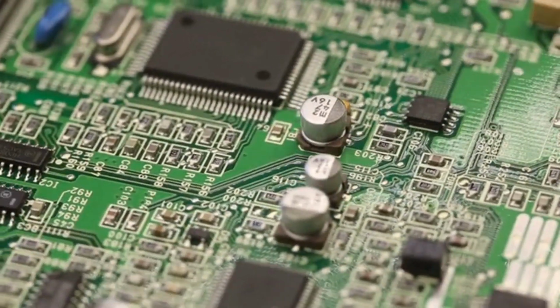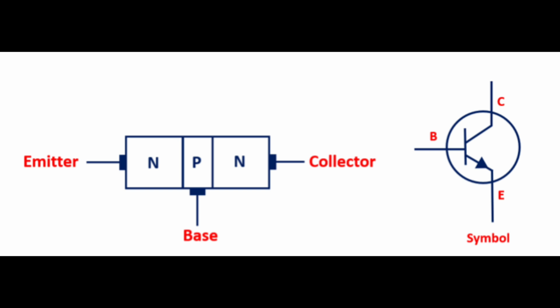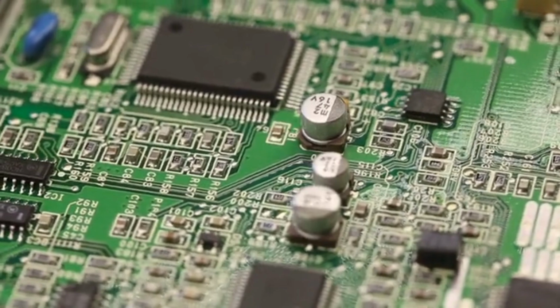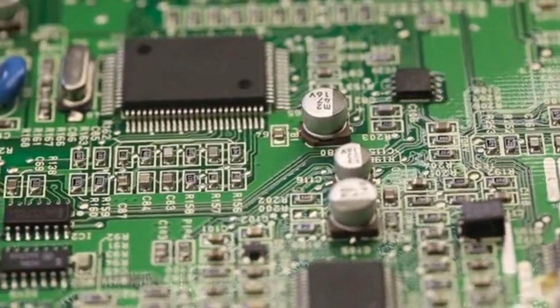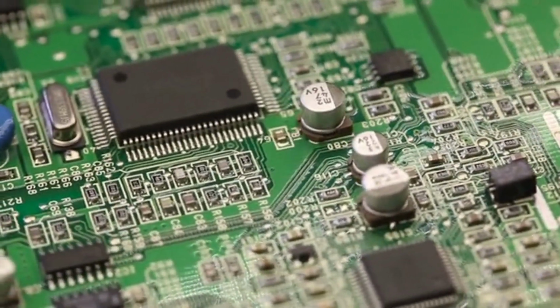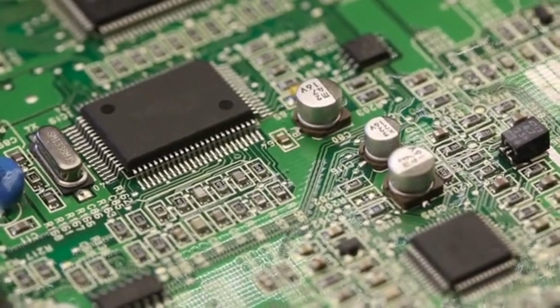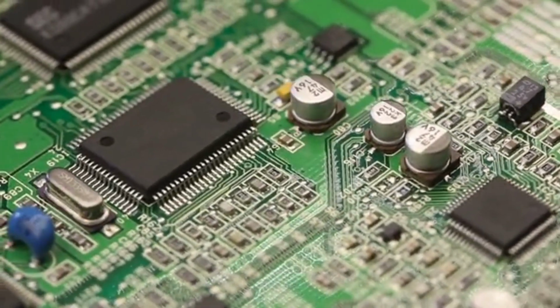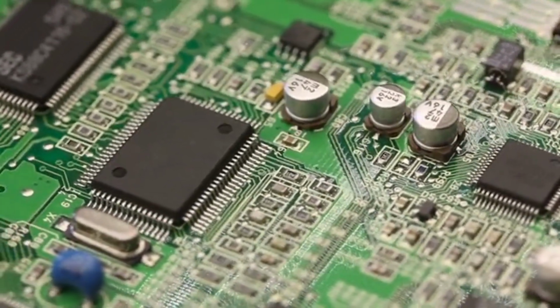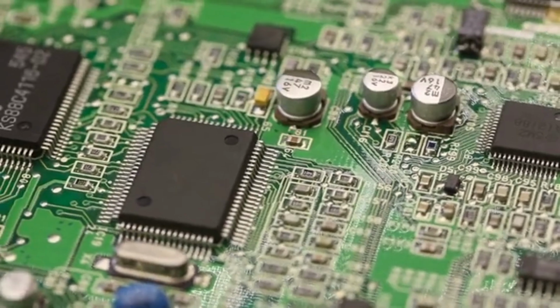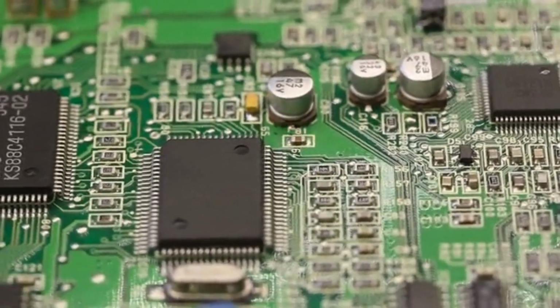We focus on the bipolar junction transistor, typically an NPN structure, a thin, lightly doped p-type base sandwiched between a heavily doped n-type emitter and moderately doped n-type collector. It essentially features 2 interacting p-n junctions. The key to its operation lies in controlling the current flow across the base emitter and base collector junctions.